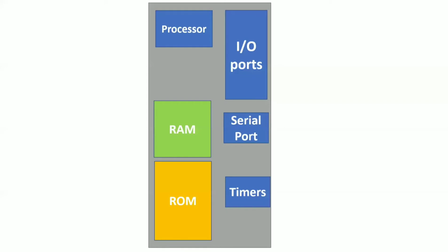Now when I'm saying a processor, the processor wants to execute the program. Whenever we are taking any microcontroller or microprocessor, you require a power supply to work on it, right? Whenever there is a power supply, there should be a working device. That's why we are having two different signals called VCC and ground. So without the power supply and ground, any electronic device won't work, right? Now VCC means plus 5 volts and ground means 0 volts. That means your 8051 microcontroller is operating at a voltage of 5 volts.